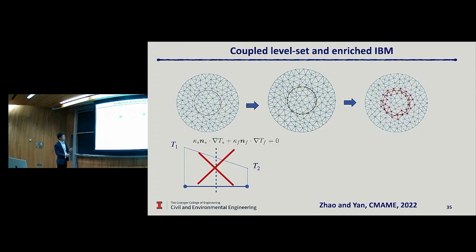So every node of the cut cell will have 2 DOF. If we are talking about the heat equation, 1 DOF for the temperature of the solid phase, the metal phase, and 1 DOF for the gas phase. Because now you have more DOF, it will give you more space to adjust your solution to satisfy this kink profile of the temperature field in the element interior.